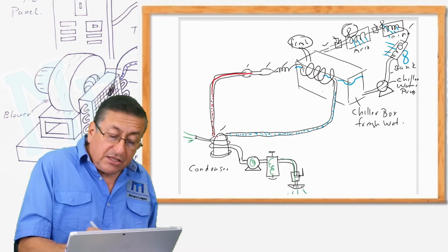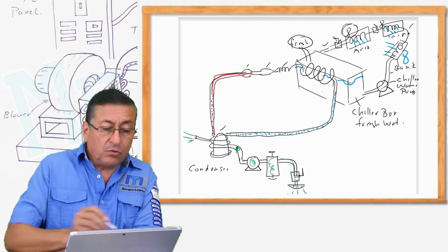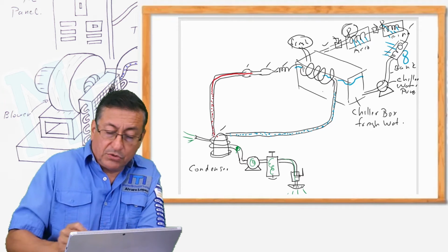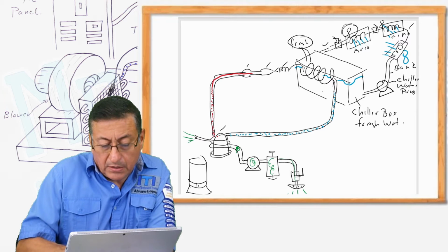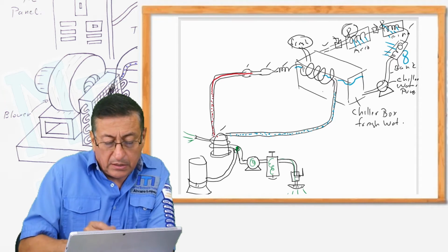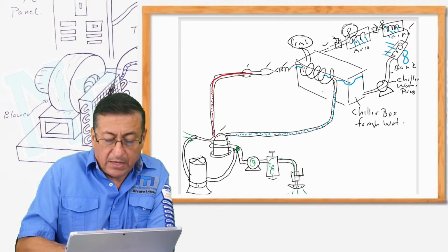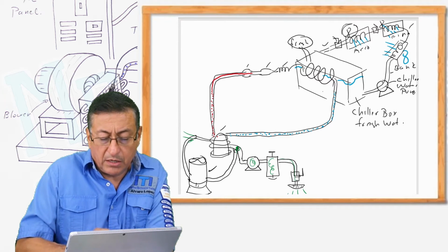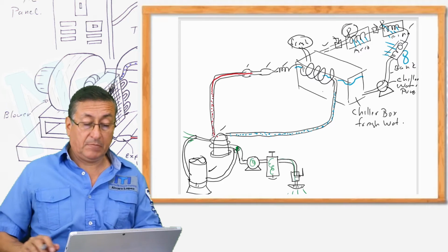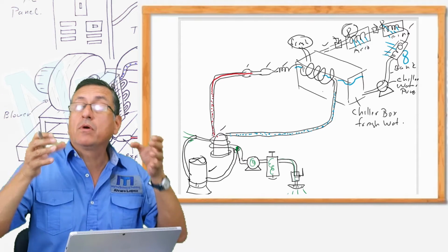It's simple. I disconnect the input of this line here. I am going to connect the cooling tower here. Let me explain. It's too simple. Okay, the cooling tower right now supplies water here, directly here. I disconnect that point, and I connect the return of fresh water here. I have a fan on top, and right now my cooling tower replaces the raw water, and the system is working with the cooling tower with fresh water.